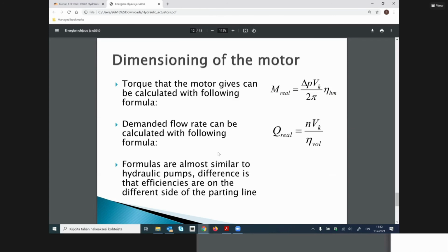The combustion engine is spinning the hydraulic pump, and then you have this hydraulic energy, and then the hydraulic energy is very easy to control, and then you use the hydraulic motors to drive forward or reverse with these vehicles, and it works very well in such a system where the driving speeds are slow, but you need a very high force.